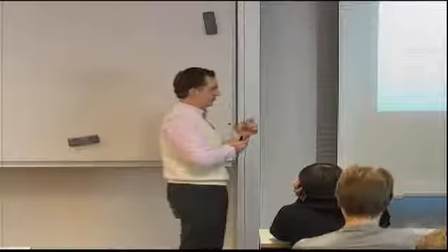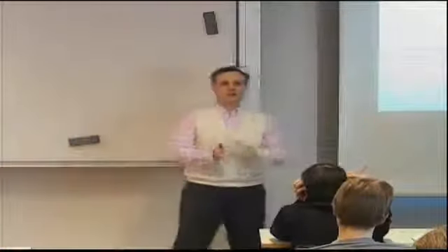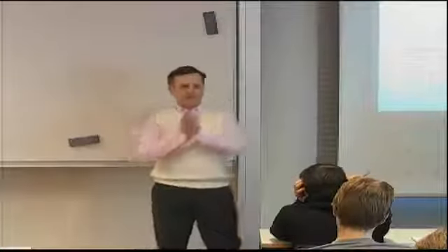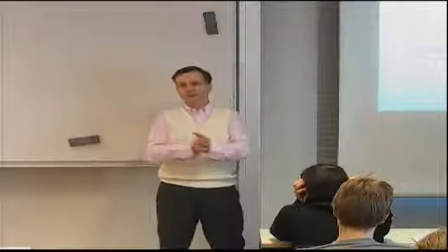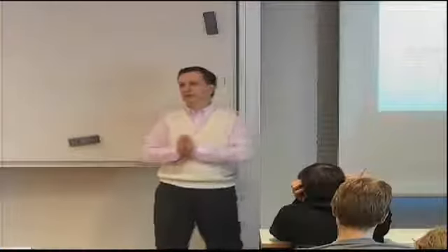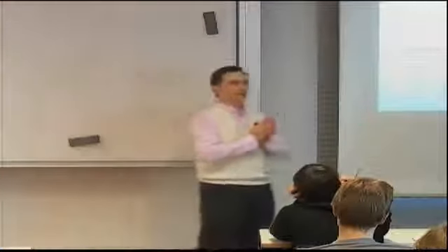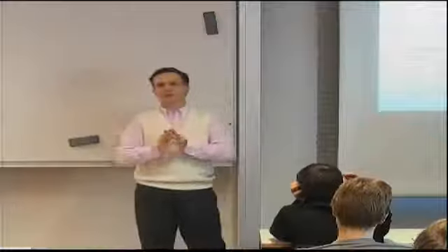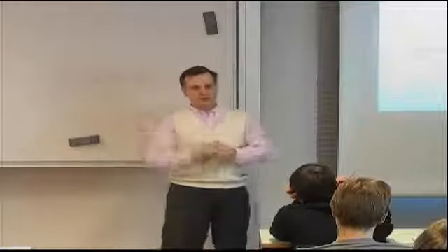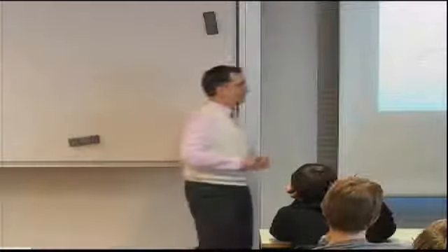Because as you will see, and that's the main message here, something that's good in buckling does not mean it's good in post-buckling. Big differences up to the buckling load, let's say at buckling load, do not necessarily translate to equally big or proportionately big differences in the post-buckling regime.